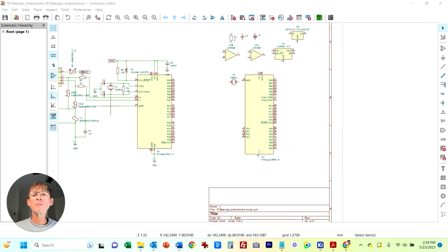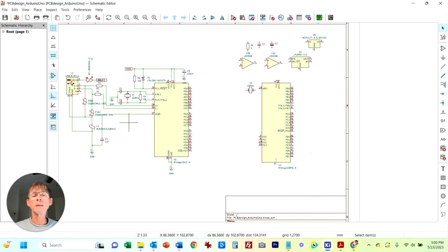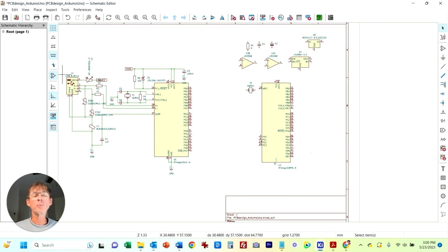So it's got a few less support components, mainly because it does not directly interface with the USB port. So you don't have the ESD and the fuse and the ferrite bead components that you have with this USB microcontroller, which does interface with the outside world more than this one does.